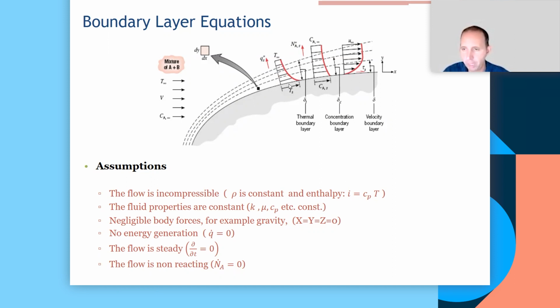If you had a very rapid change in the shape, perhaps if it was to drop suddenly and create a step of this nature, then the flow is quite likely not going to be able to follow the contour unless it's extremely slow or unless you have perhaps a very low Reynolds number. If not, you will get what is called boundary layer separation.